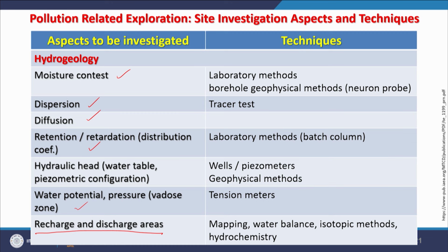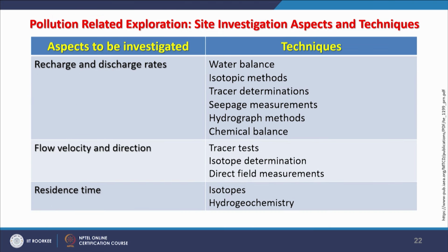No recharge site should ever be chosen for any kind of waste disposal site. Simple reason: it will directly pollute our groundwater aquifer, whether the aquifer is confined or unconfined. So, that kind of study or knowledge about that area is very much required, for which you need geological mapping, water balance, isotopic studies, hydrogeochemistry, all kinds of things. For recharge and discharge sites, you need to know the water balance, isotopic methods, tracer determination, seepage, hydrograph and all kinds of things.